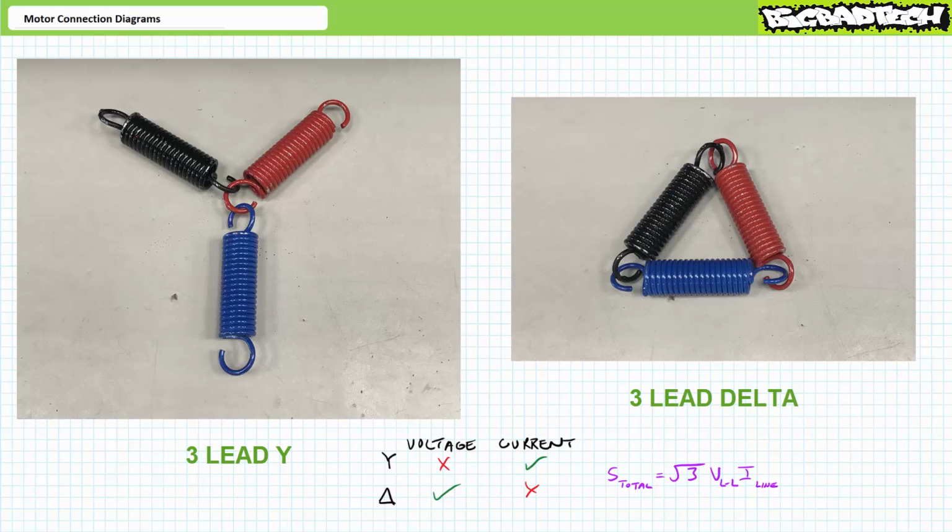For this reason, when working with balanced 3-phase AC systems like 3-phase AC motors, one customarily employs what is known as the single wattmeter method, which utilizes measurements entirely external to the motor. A line-to-line voltage measurement is external to the motor, as is a line current measurement. Total apparent power delivered to the motor is equal to square root 3 times the line-to-line voltage times the line current, regardless of the electrical configuration of the motor, Y or delta.